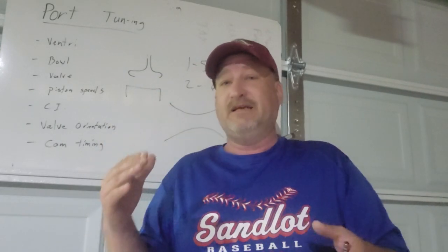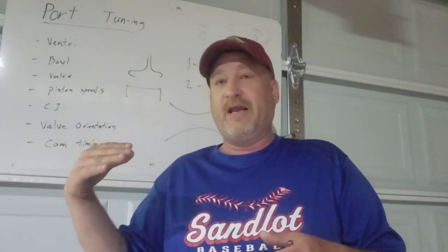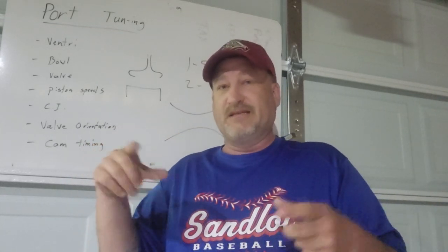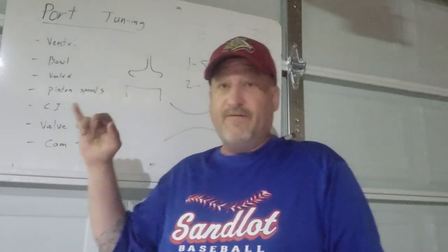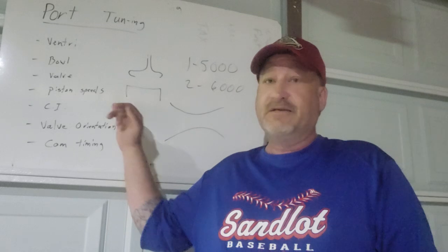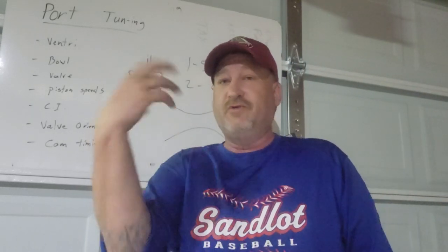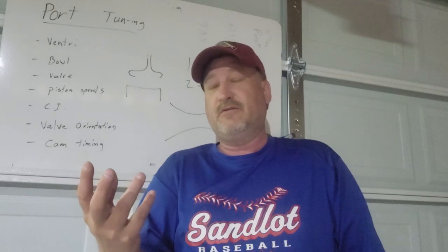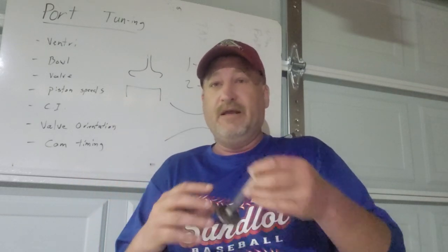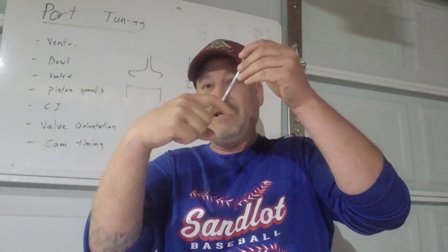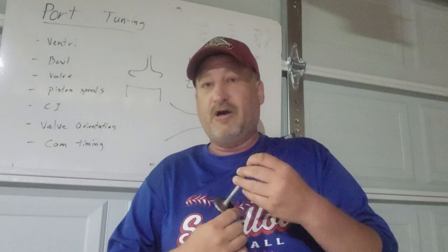The higher velocities normally travel at the top of the port. So by having a ramp on the short-turn radius, the vacuum being pulled over the short-turn radius from the valve and the cylinder is pulling the heavier fuel molecules up into the faster portions of the velocity of the port and the air movement. They meet basically at the back of the bowl area and on the valve at lower RPMs.